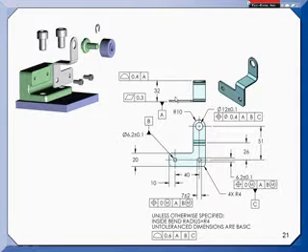And that would look something like this. A is the mounting surface, B is this hole, and C is the width of that slot. When I present this in class, time and time again, when I ask what the datum features should be, people will say, how about these outside edges? Well, as you look at this drawing, those outside edges are just there to hold the holes.